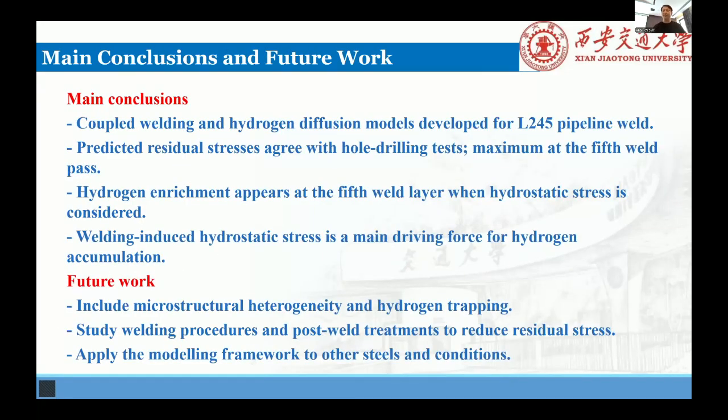Before closing, I briefly summarize the main conclusions and future work. The main conclusions are as follows. First, the coupled welding and hydrogen diffusion models have been successfully developed for L245 pipeline welds. Second, the residual stress predicted by the welding simulation agrees well with the hole drilling measurements, and the maximum circumferential and hydrostatic stress occur at the fifth weld pass. Third, when the hydrostatic stress is taken into account, hydrogen enrichment clearly appears at the fifth weld layer.